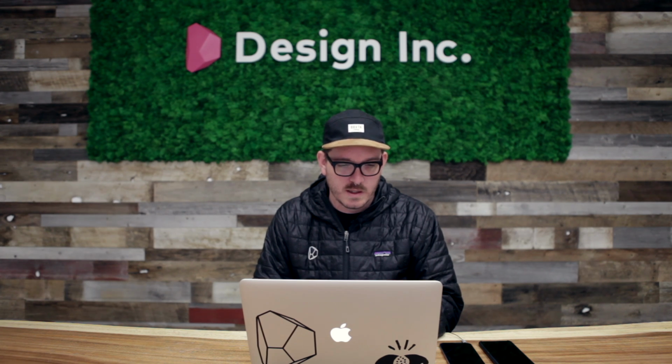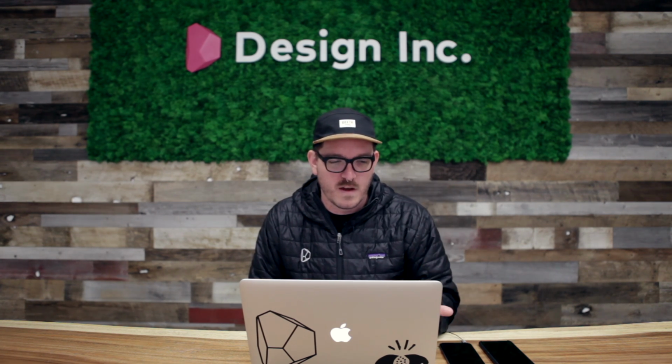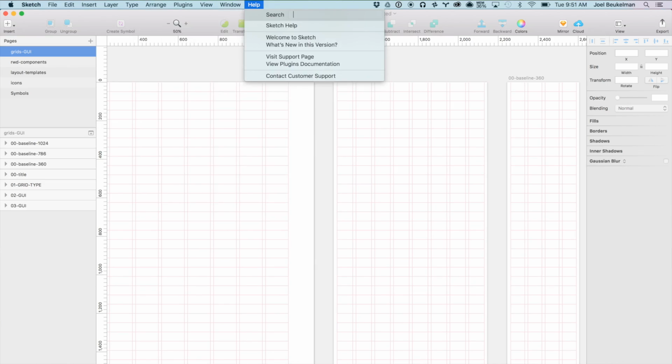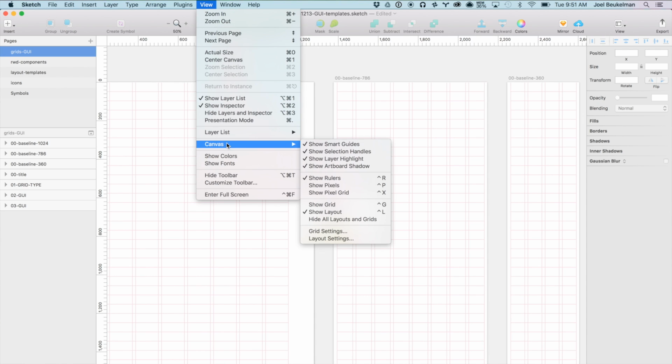I can show you a little bit of how I've set up my file, and I'll probably share this file and let it be downloadable as far as the initial template. It's nothing fancy, but I figure I can share it if it gets you off to a good start. Okay, so if you go under View and then Canvas, you have all these different options of what you want to show in the actual workspace, as well as being able to set your grid and layout settings.